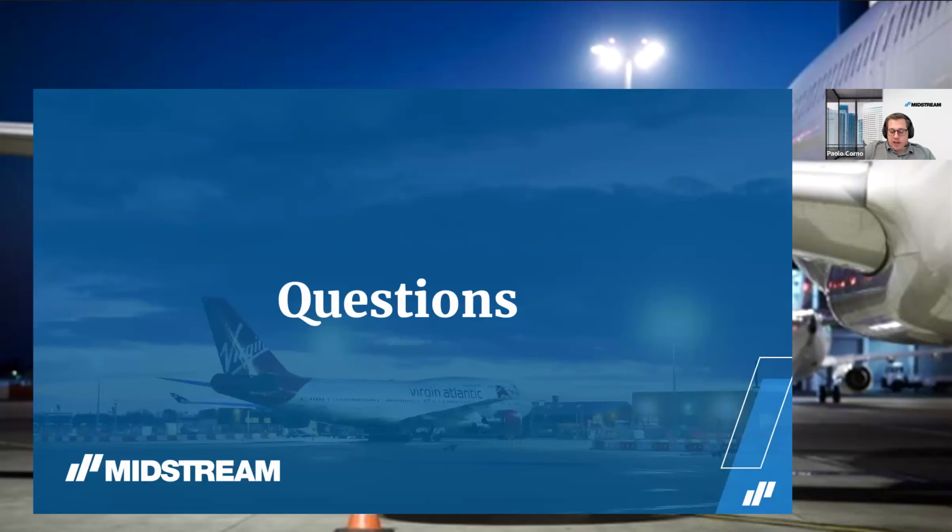As we touched on before, ICAO does not tell you how to measure nor where to place the points. That is a task of lighting normatives that define the number of points. So again, the exact number of points needed for a uniformity calculation is given by a lighting normative, whatever the local relevant one is. And it's a result of a formula taking into account the size of the area. For practical measurement, the minimum for an apron that size is 25 points.